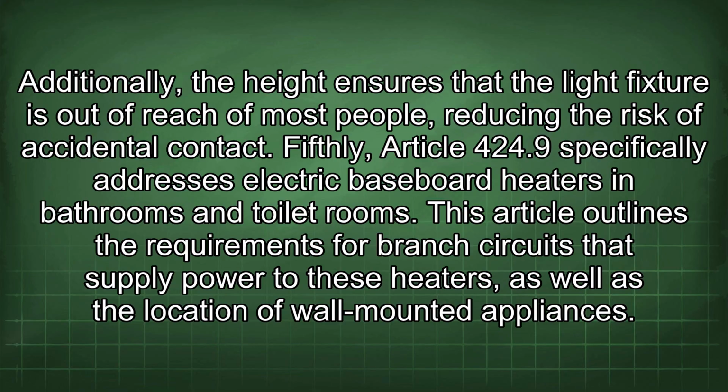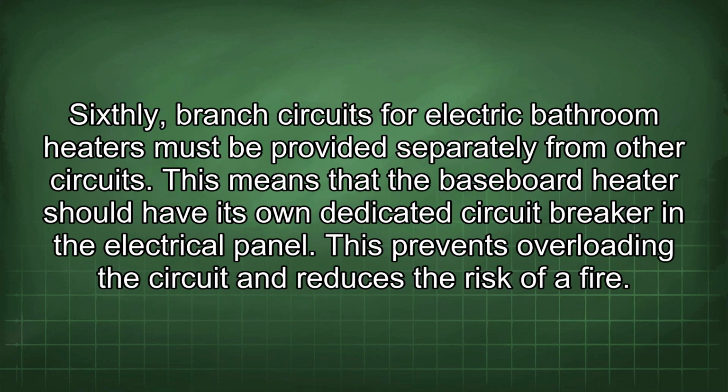Fifthly, Article 424.9 specifically addresses electric baseboard heaters in bathrooms and toilet rooms. This article outlines the requirements for branch circuits that supply power to these heaters, as well as the location of wall-mounted appliances. Sixthly, branch circuits for electric bathroom heaters must be provided separately from other circuits.